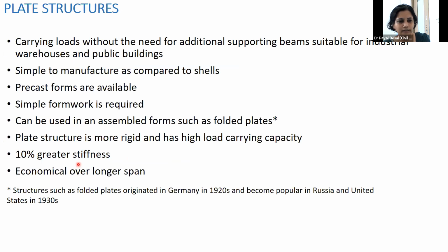Now, why are plate structures so popular? One thing is that they are very efficient in carrying loads. The thickness is very small, but the other dimensions are very large. First, the load carrying capacity of plates is much stiffer compared to beam bending and other types of structures. Also, you can cover larger areas without the support of beams and columns, and mainly it is suitable for industrial buildings, warehouses and public buildings.